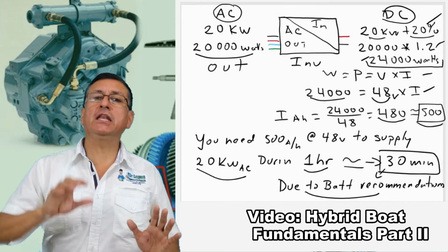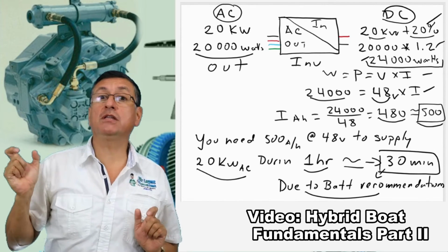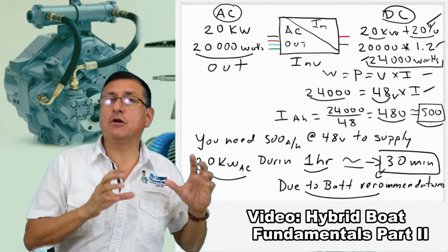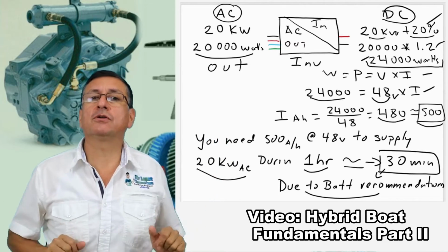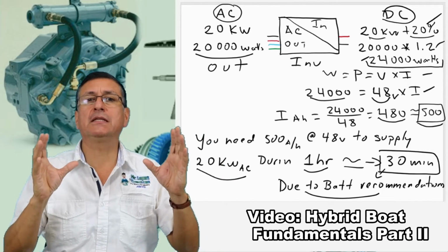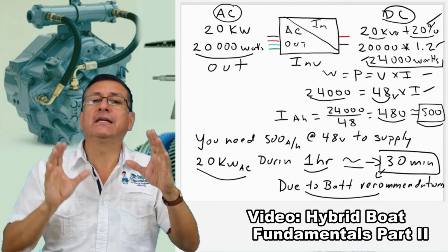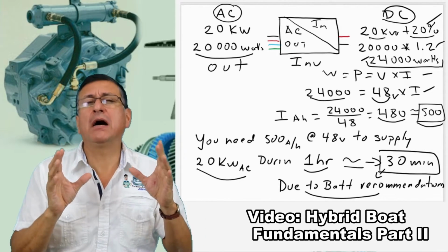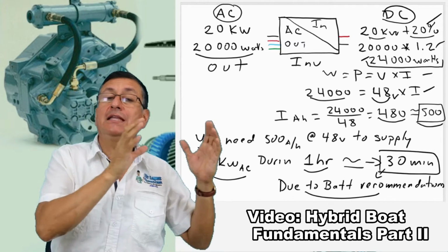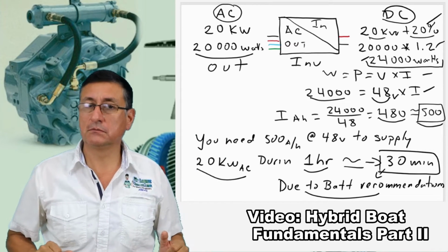How much power do I need to put in the input? You need to put exactly the same that you need in the output, plus some additional power, because internally the inverter dissipates power, heat or drag. How much? Like 17%. For that reason, I need to add in the input 20% additionally for safety factor.